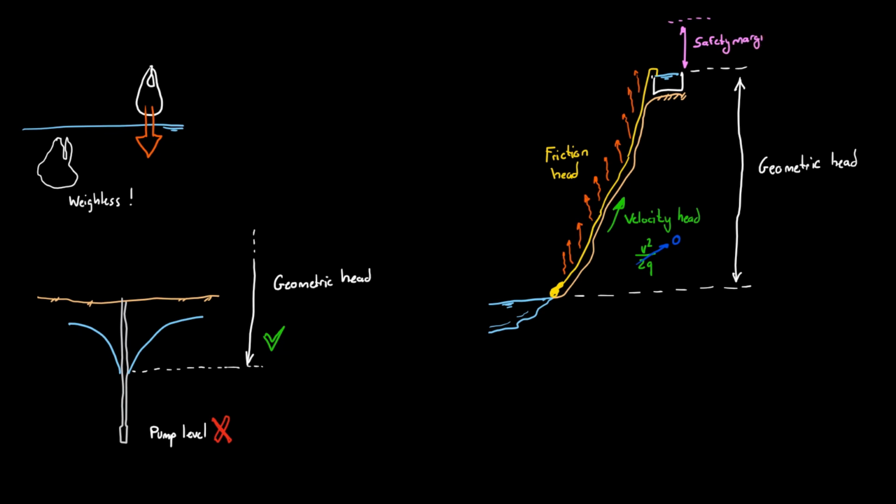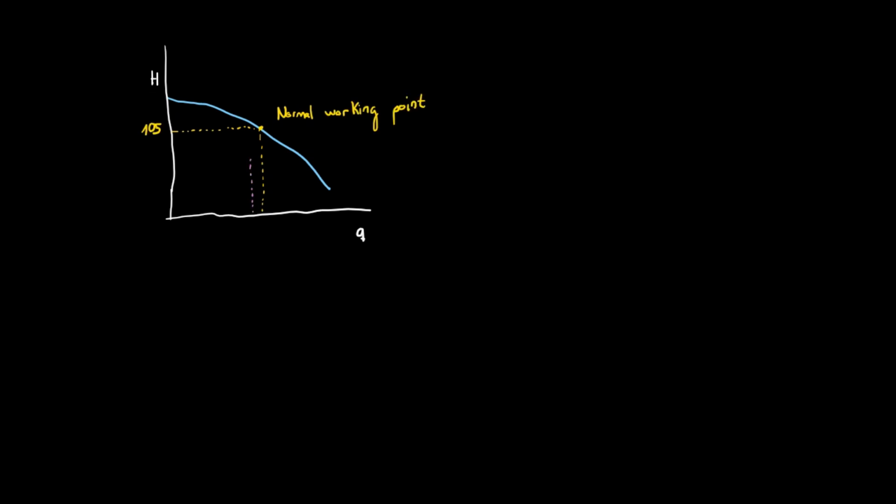And how about the usual 10-meter safety pressure margin in water supply schemes? We don't need it. The pump can move its operation point to compensate for any errors or unpredicted circumstances. The flow will be slightly less, but we can easily pump a little bit longer.